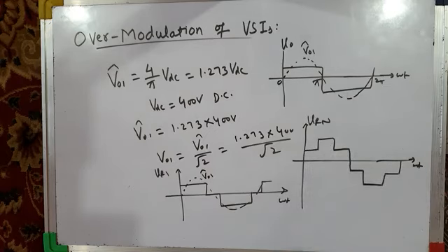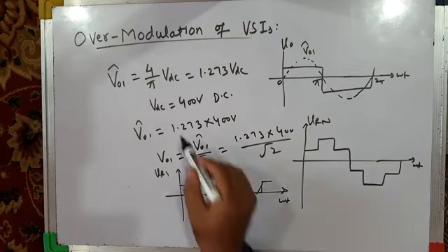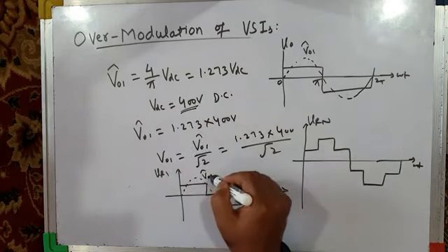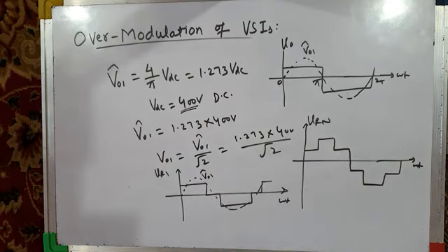When you are operating a three-phase voltage source inverter in square wave mode or in 6-step mode of operation, you get, no doubt, maximum fundamental output voltage. That means you get the best utilization of DC bus voltage. From a given DC bus voltage, you are able to produce maximum AC output voltage, but at what cost? At the cost of very high distortion in the inverter output voltage, which again is unacceptable in most applications.